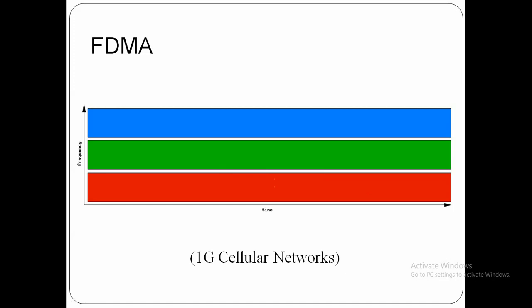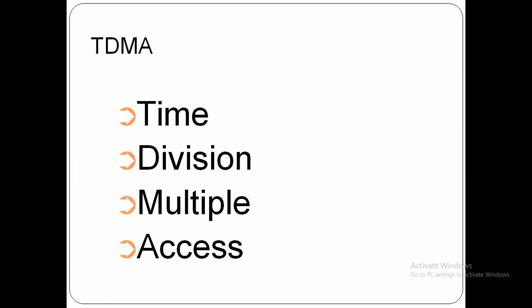In FDMA, the difficulty of assigning multiple channels is due to the inability of the radios to simultaneously demodulate the received signals. The transmission in FDMA is continuous over time. FDMA is also used in OFDM systems, with multiple carriers used for each user. Having some features, we see them step by step. First, FDMA we have seen here diagrammatically.